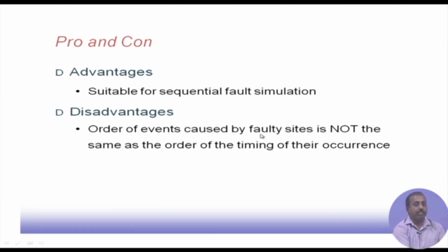Advantage, it is suitable for sequential fault simulation. Disadvantage, the order of events caused by faulty sites is not the same as the order of timing of their occurrence. What we mean is that the gates have some order in the circuit: when we simulate one particular gate, its predecessor must have been simulated.